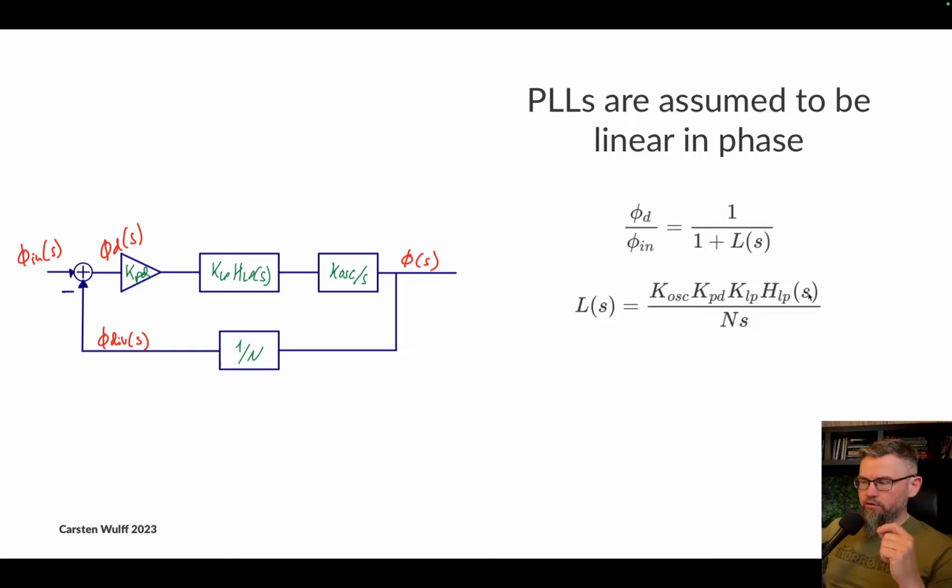So let's, for example, assume that our loop filter here has a low pass response, which means that at low frequency, it's basically a constant. It doesn't change much with frequency. It's only at high frequency that it actually rolls off and becomes less. So let's assume that's a constant. And then we insert 0 into this loop filter equation. Well, if we insert 0 frequency, so we take the s, we replace it by j omega, we insert 0, then we get an infinite gain here.